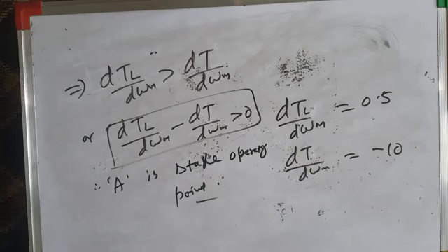So therefore, whenever you design a drive and you find the motor torque speed characteristics and the load torque speed characteristics, you plot them, find the operating point, and using this logic you find whether the operating point is stable or unstable. If the operating point is stable, go ahead and design the drive, and then the drive will operate stably. Otherwise you may have to choose a different type of motor for that particular type of load, which gives a stable operating point.